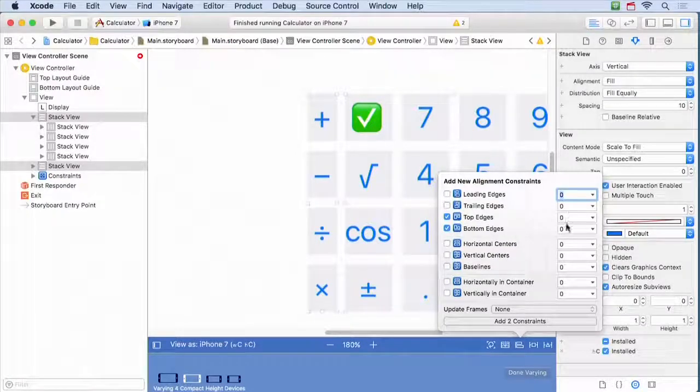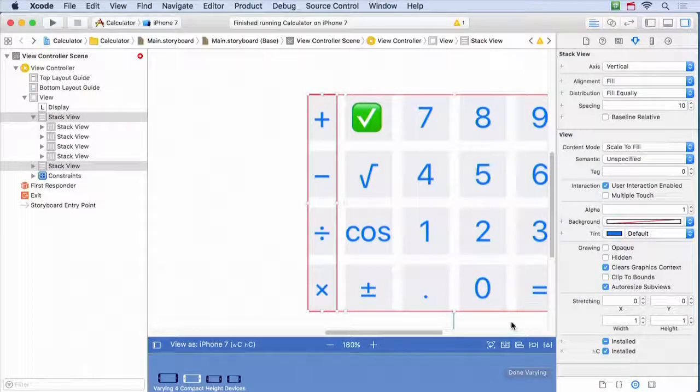These numbers over here, by the way, are an offset. So if you wanted it to line the tops, but you want one to be 10 higher, you could put a 10 in here. But I want them to be right along the top. I want to have the constraint where this is exactly the same and this is exactly the same at all times. So I pick whichever I want and just say Add Constraints, and I added them. Now, whoa, it turned red. Why am I getting those red lines right there?